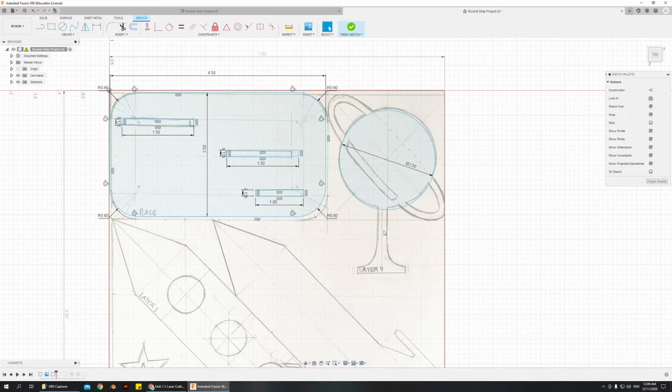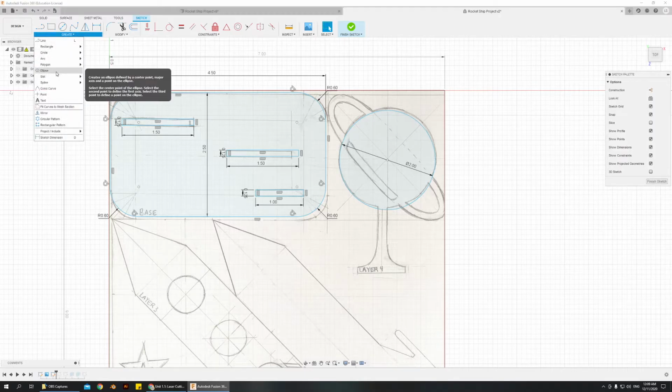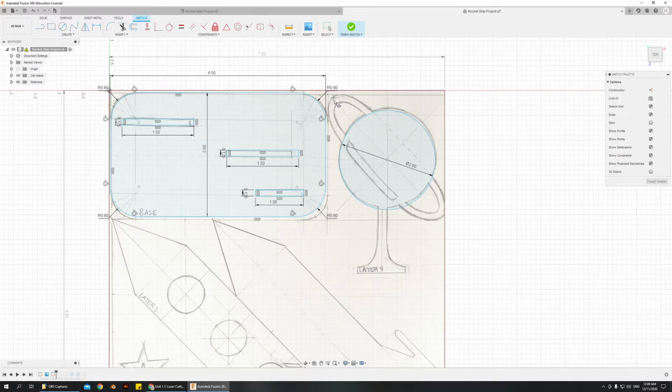And then down in this menu here, there's an ellipse tool. So I used the ellipse tool to create an ellipse, but actually it's a center ellipse for that one. So it's ellipse from here to this edge, done. And then the width is gonna be the width that I want to there, let's say.